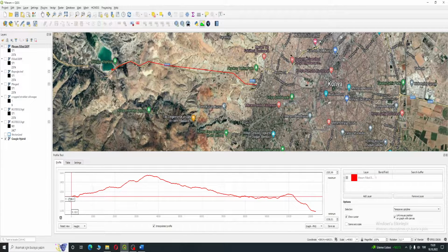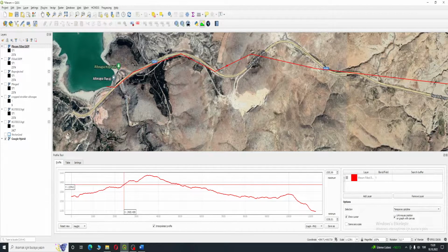But if we use the Darcy-Weisbach equations, you know that our water loses its energy, and maybe our water cannot pass through this distance, because water goes from this lower altitude, and at some point it has to climb this peak point, and after that the water goes with gravity force.